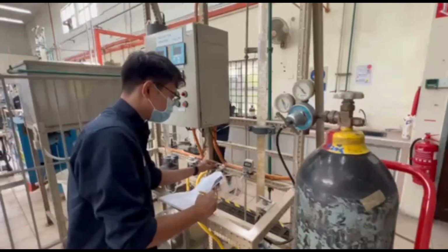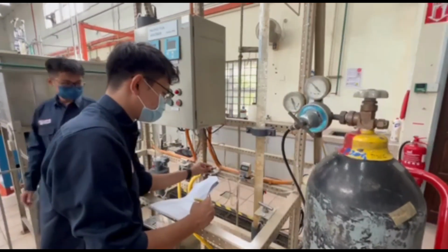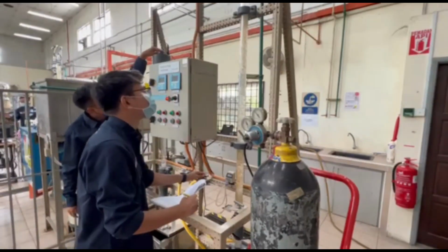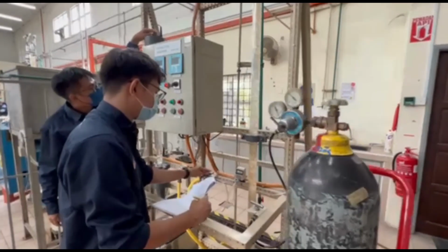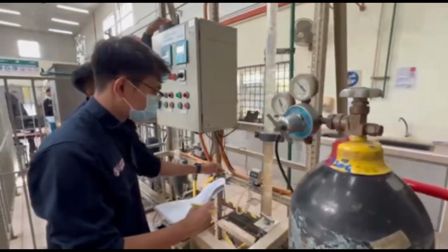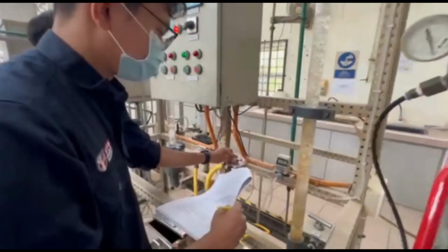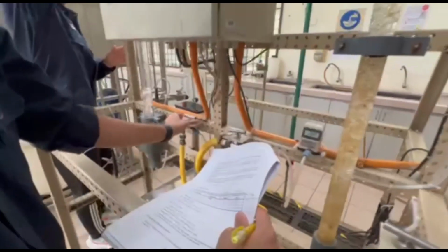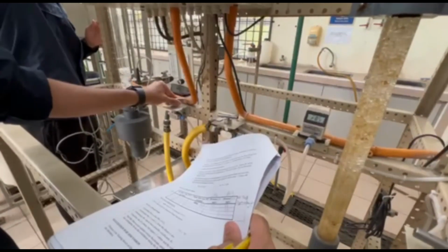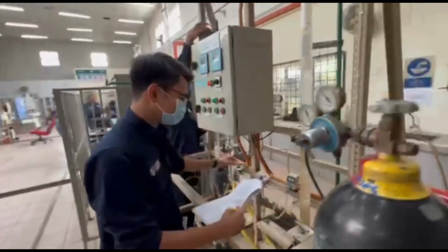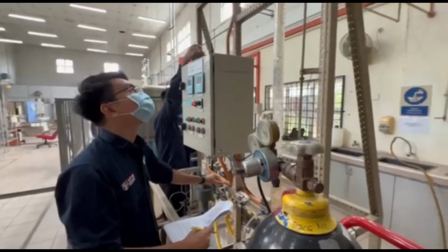In this step, we are opening our valve V1 and setting the air flow rate to our desired flow rate. We also need to monitor the water level in the deoxygenation column by adjusting our V3 valve. The water level in the deoxygenation column will always fluctuate, hence we need to monitor both valves simultaneously.